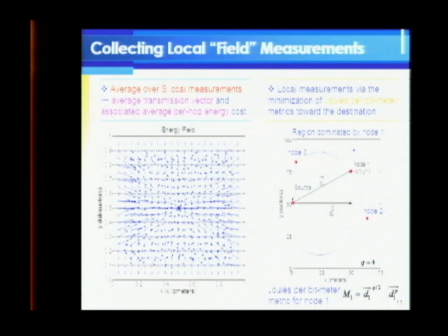We use a heuristic scheme based on a joules per bit meter metric. Here, this is the source location located in some cell, and this is the direction towards the base station. So the base station is located somewhere here. Whenever we use a certain transmit radius, and whenever we find a neighbor, we measure the energy consumption to reach that neighbor. And we also look at, because we have position information, how much headway it would make towards the destination. So in this case, it would consume this many joules of energy per this many meters towards the base station. You see that the nodes that are close but do not make headway towards the base station are penalized, and also the nodes that are good in terms of their projection to the base station, but would consume a large energy, are also penalized.